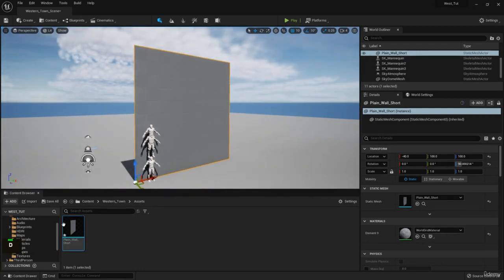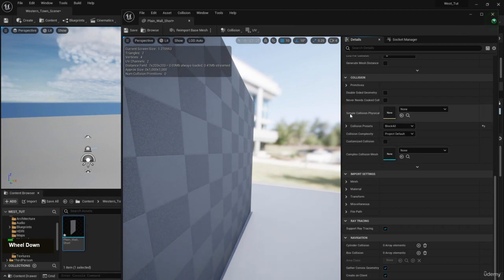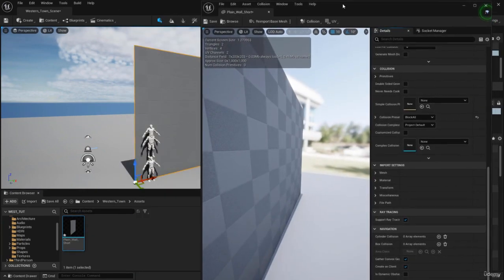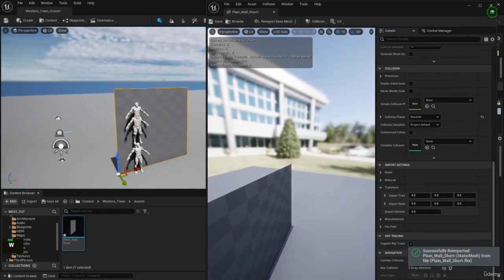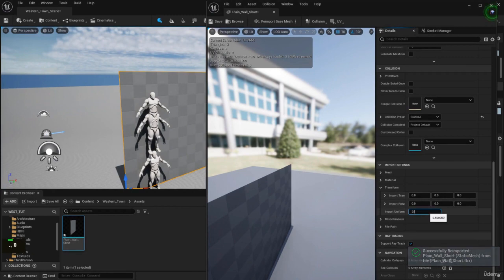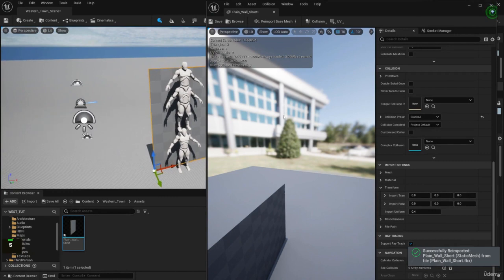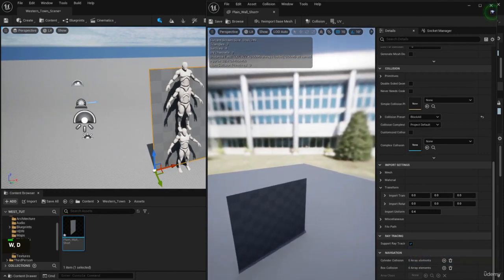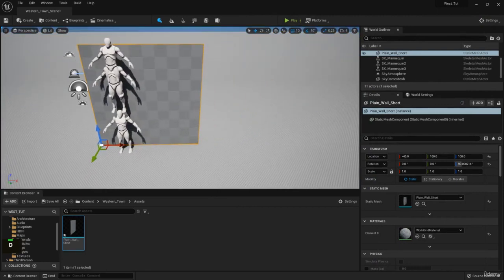So for now, we can see this over here. What I'm going to do is set my scaling down here. If you double click on your wall short, you will open up the mesh editor. And if you go down to transforms, let's set this to 0.5, for example. It's a bit of a weird one. The scaling is behaving a little bit strange. But as you can see, 0.4. Then we are just going to set the scaling inside of this one. So over here, in the end, the primitives will stay the same. We will have even spacing, which means that if we...